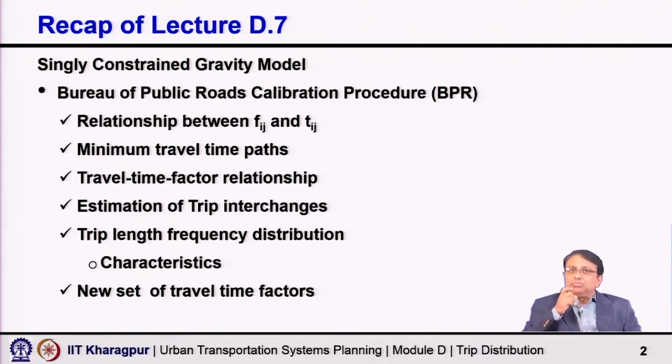As I said, the total 5 minute travel is matching, so how travel time is acting as a deterrence is grossly matching. But if total 10 minute travel is matching, and if travel time is the only factor influencing this trip distribution, then the multiple cells which have the same travel time should automatically match, because my overall gross percentages or frequencies are matching.